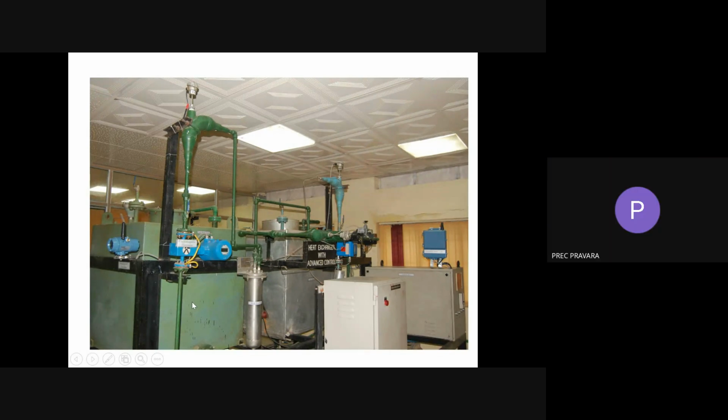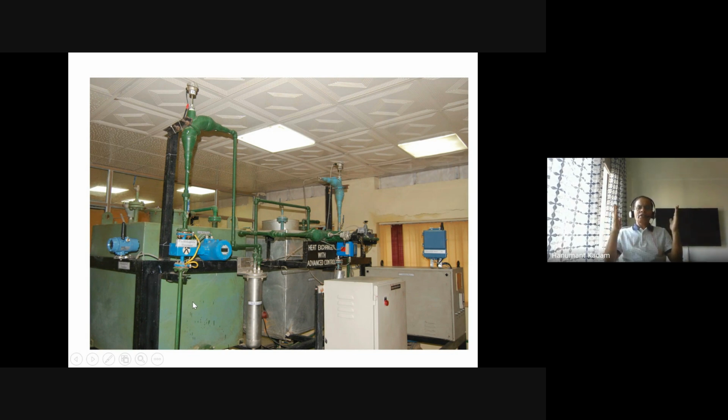So in this slide, you can see one plant where an electromagnetic flow meter is installed. You see a very small pipeline, but you see how it is installed. Here I will demonstrate the flange connection, and inline mounting means this is the mounting here. And these are the flanges. You can see on the pipeline side two flanges, upstream and downstream. This is the arrow showing the flow direction. The flow is going like this, it is water flow, and water is also conducting, so we can use this. You see here, these are the flanges of the magnetic flow meter body.